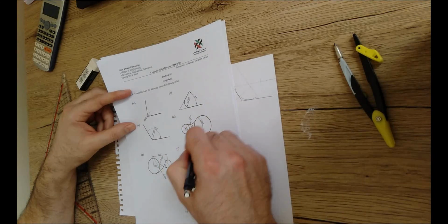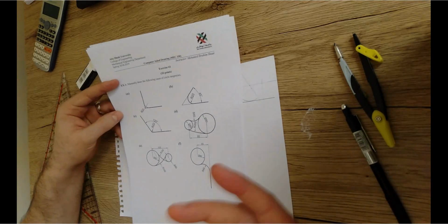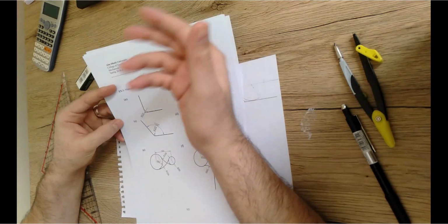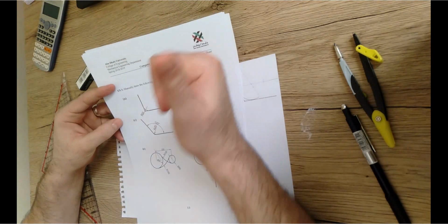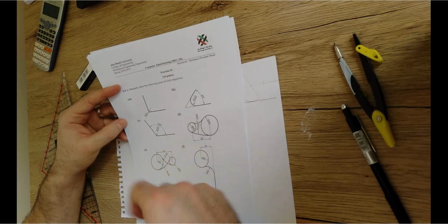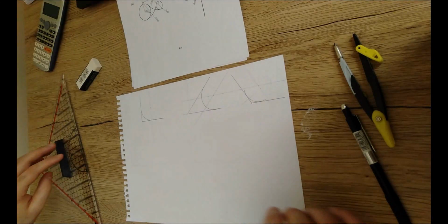Then we can work on the tangencies here of the other two curves. So it means that, and this is basically what we did for the lines. We draw the line first, then the last thing, we draw the curve that is tangent to the two lines. So we're gonna do the same for the circle. We have to draw the circle first, and then we're gonna draw the curves already using the tangencies concept. So let us draw the circle.